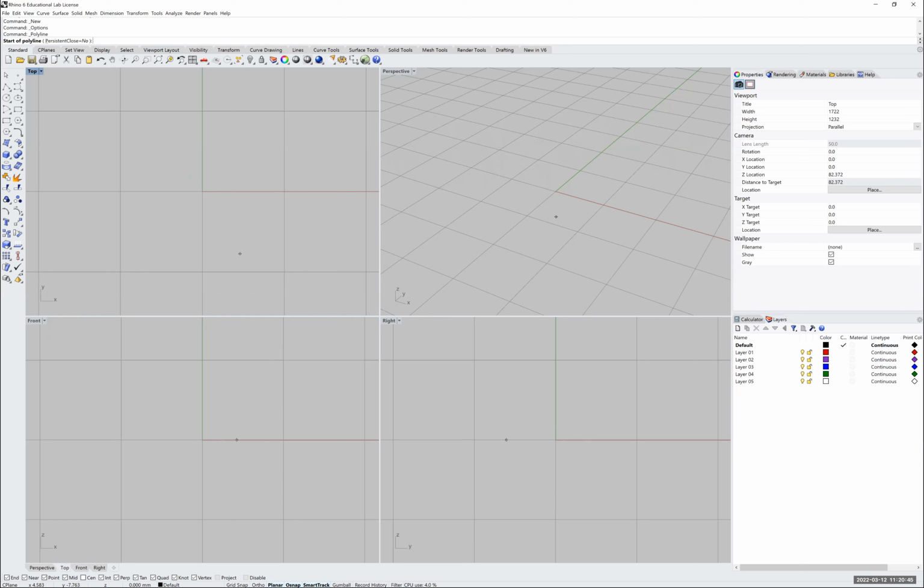Now, if you look slightly more towards the left side, you can see that I have a set of options, just like with AutoCAD. I can snap to grid. And you notice how if my text is in bold and the background is in light blue, that means the command is activated. If not, just like right now, this command is not activated because the text is not in bold and the background is gray. I can also turn my ortho mode on, and as we mentioned earlier, ortho means I am restricting the movement of my lines to be parallel to the X and Y axis.